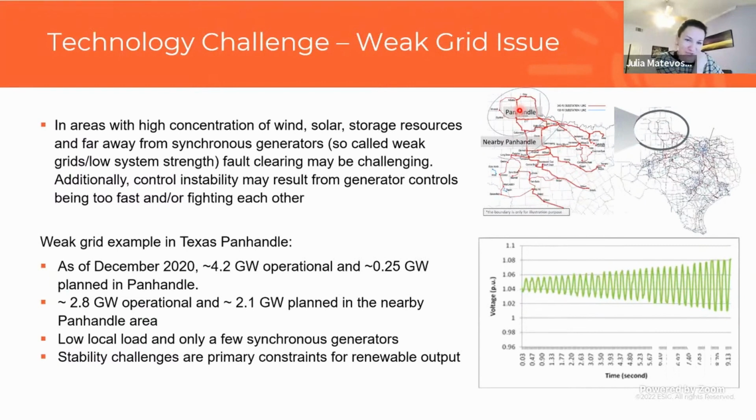It hasn't been used yet, but what worries me is that they have about 7 gigawatt of batteries in the interconnection queue with already signed interconnection agreements. So these projects are relatively likely to materialize. And none of these projects is currently being designed as grid forming because there is no incentive, no requirement from ERCOT to have grid forming inverters on the system, and there is no market for some kind of product like what they have in GB that prompted some of the grid forming inverter development.